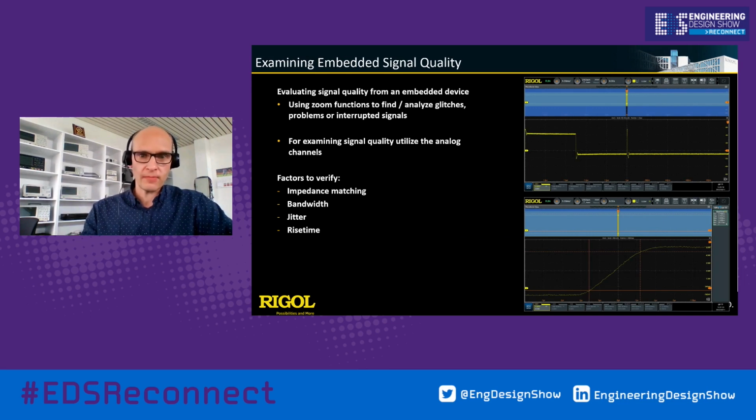This oscilloscope can also be used to collect a big data stream, and thanks to the very deep memory of maximum 2 gigapoints and very high sample rate of 20 gigasamples per second, we have the capability to zoom in and also make a deeper analysis of this big stream of data. For example, it's easily possible to zoom in as in the picture above and to see some kind of glitches and go deeper into the analysis of such glitch effects. Furthermore, it's possible to go deeper and make measurements like rise times or bandwidth effects to see if we have good impedance matching in our data stream.